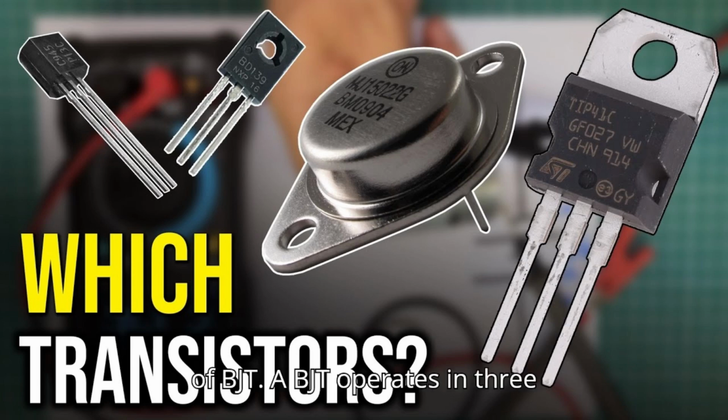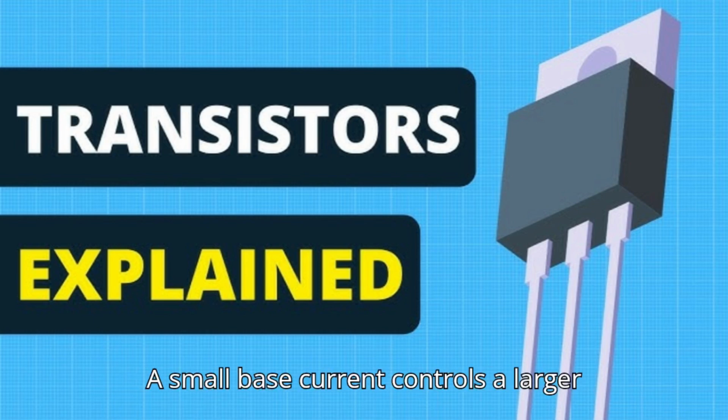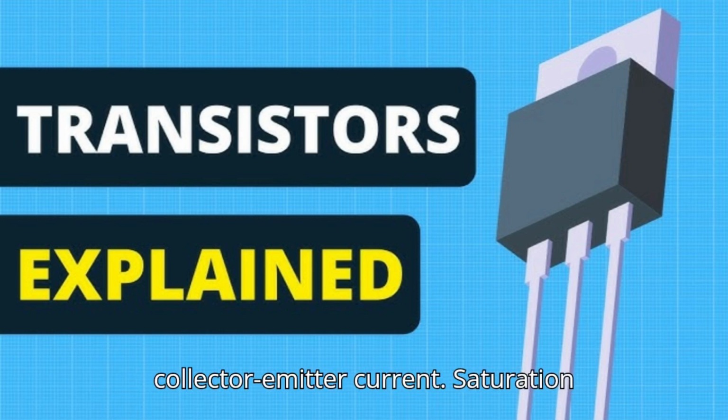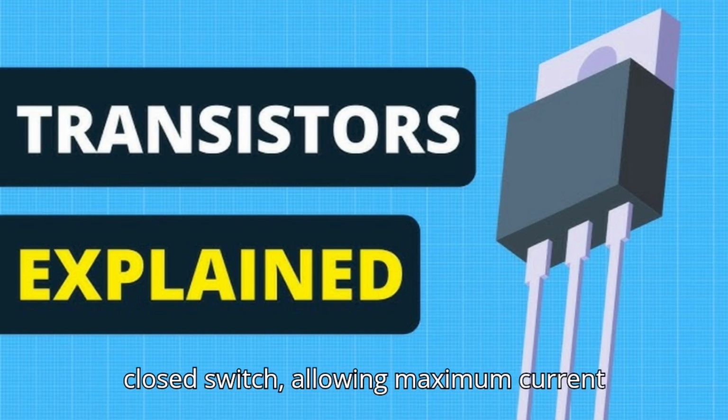Working of BJT. A BJT operates in three modes. Cutoff mode, OFF state: no current flows from the collector to the emitter. Active mode, amplification: a small base current controls a larger collector-emitter current. Saturation mode, ON state: the transistor acts as a closed switch, allowing maximum current flow.